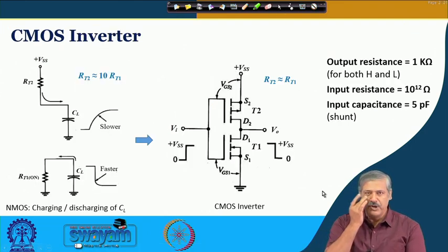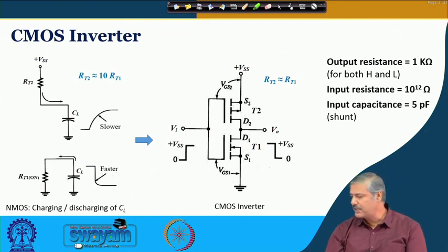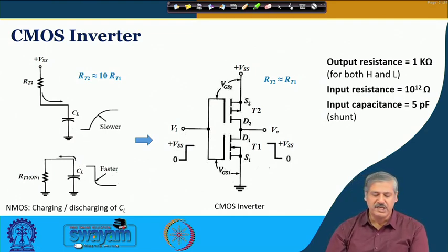Okay. Because of which, in the NMOS based circuit, we are having an issue: the output, where the capacitor plays a very important role at the output junction, charging and discharging of it, because the current the next stage will take is very low, of the order of picoampere or so.